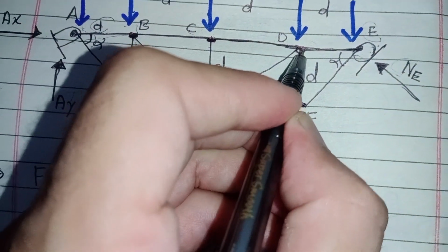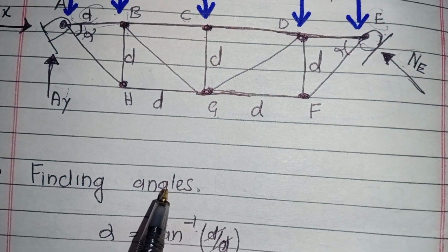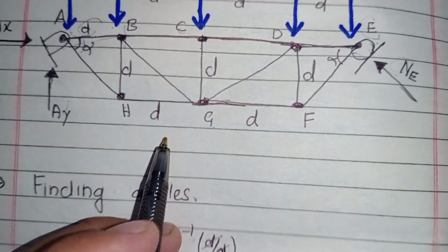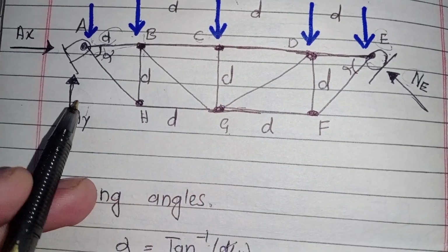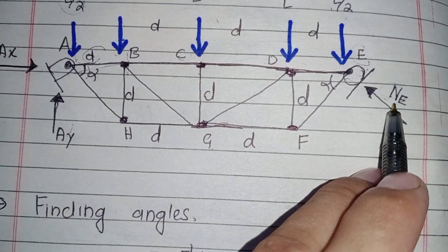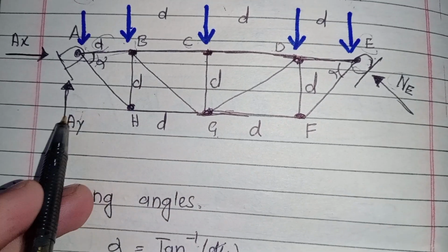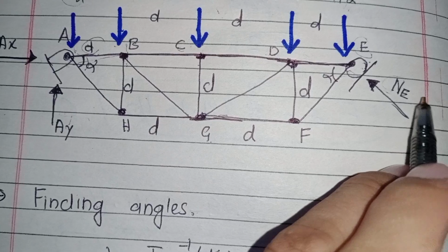So first of all, we have to isolate this whole truss, show the reaction forces in the free body diagram, and find all these reaction forces.